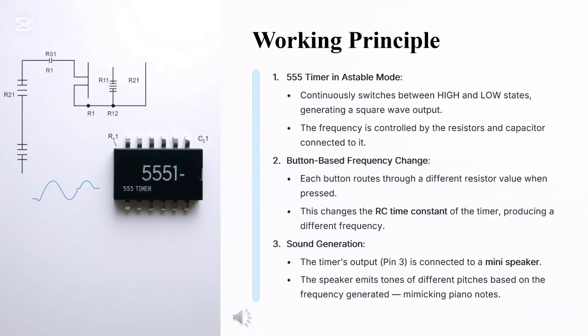Pin 6 and pin 2 will allow retriggering of the 555 timer IC after every timing cycle. So we will connect these pins together to the ground through a capacitor. The output pin 3 is connected to the speaker through a 10 microfarad capacitor, and the fourth pin is connected to the VCC to avoid any sudden resets.